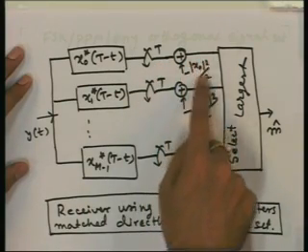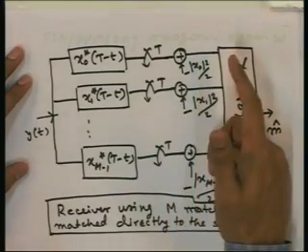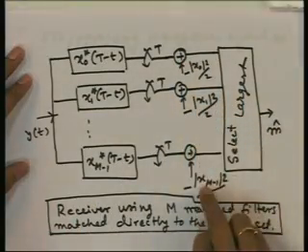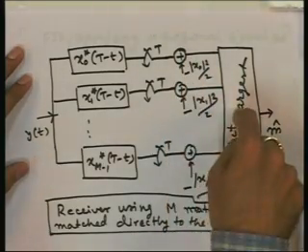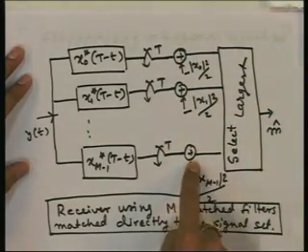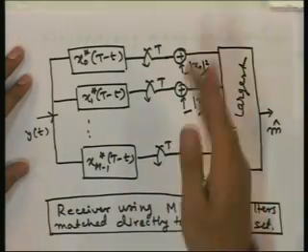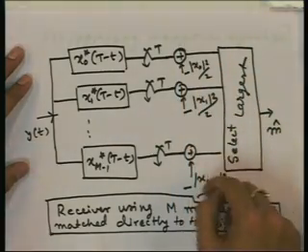this also need not be done now, because for FSK and PPM or for any orthogonal modulation technique, we have discussed that the energy of each signal is the same, E. So, this mod x naught square is the same as mod x1 square and so on. So, they are all the same. We are adding the same quantity to each and then comparing. So, this need not be done. Whichever is largest here will be largest here also, because we are adding the same quantity to all of them, because all these are the same.